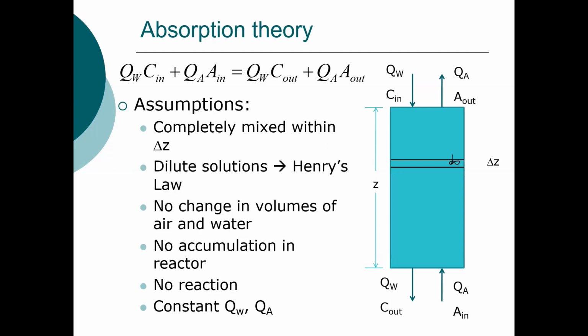So within this small parcel of air-water mixture, we have complete mixing. We'll assume, as I've mentioned before, that when we have dilute solutions, we can use Henry's law so that the concentration in the aqueous phase is equal to Henry's constant times the partial pressure in the gas phase.